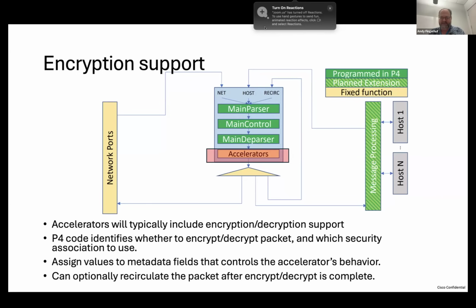It's a little bit belittling sometimes when I think of this, maybe, but most of my work developing programmable NICs and switches is not because you can't do these things on a general purpose CPU, it's because it's way cheaper and uses less power to do them per packet on these devices. Doing specialized gates for things is usually the way to get the best price, power, performance ratios. If it's something you want to do on every packet at line rate, doing it in a general purpose CPU is often a bad choice. So, okay, thanks. But yes, they certainly can be done in ARM cores or whatever, but that's really a vendor choice.